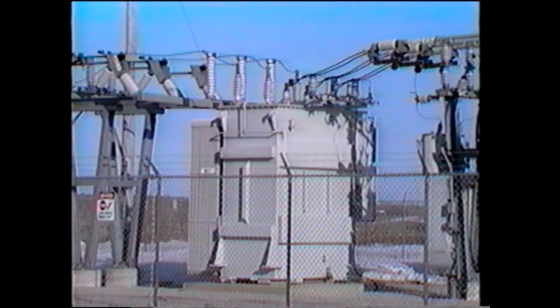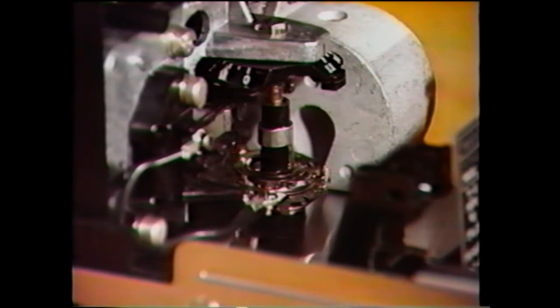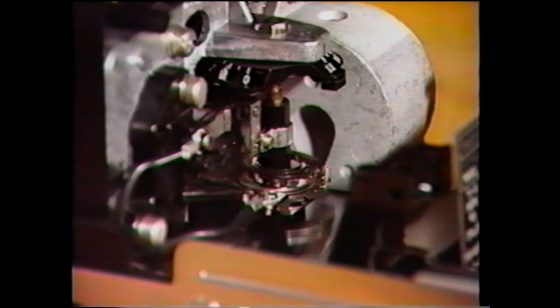For smaller transformer banks in the subtransmission and distribution systems, a simpler differential relay without harmonic restraint may be used. The operating element consists of an induction disc. This operates quite slowly, about 0.1 seconds, so it will not be responsive to the short-term inrush current. In yet another method for preventing tripping due to inrush, the operating coil of the differential relay is desensitized for a few milliseconds when the primary breaker is closed.